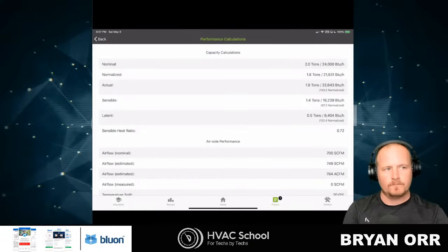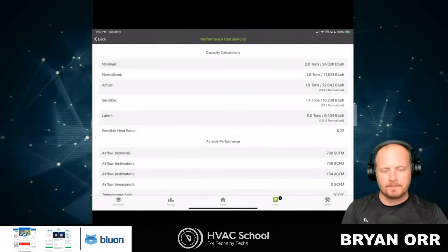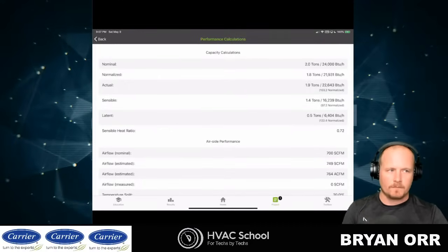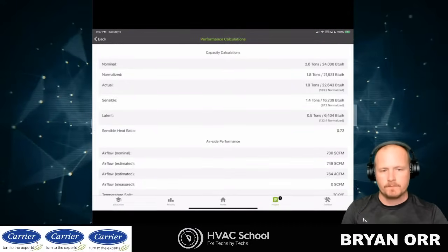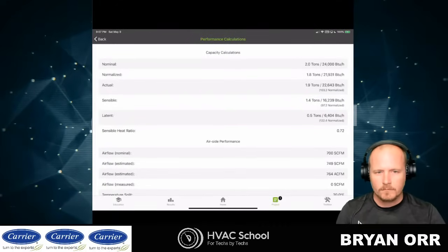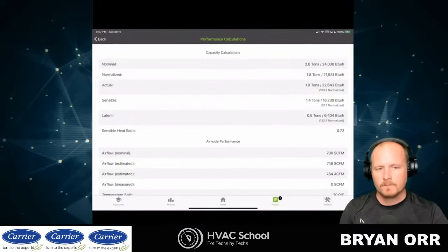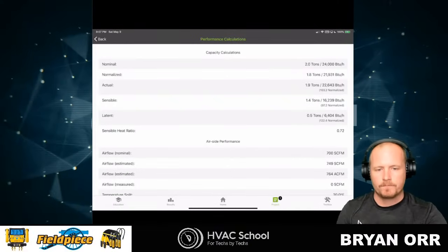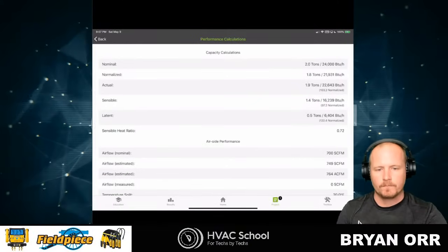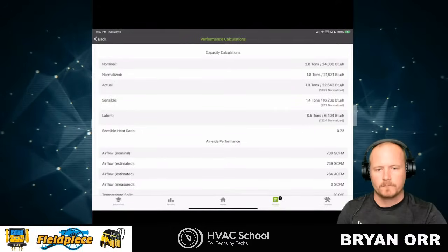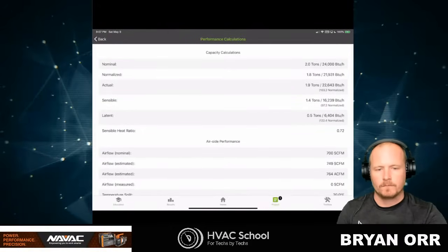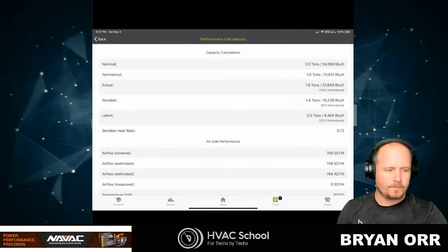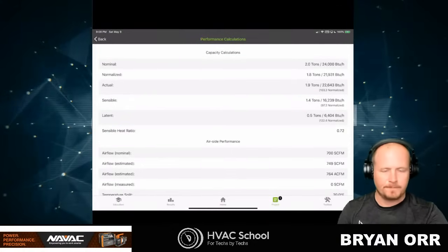So in other words, what do we expect from that 2-ton system? Well, we take into account the return air, wet bulb and dry bulb, the outdoor air temperature, the line set length, the voltage, airflow. All those things contribute to how much cooling we're going to get out of that thing. And so we normalize the capacity. So under the load conditions you're at now, if it was the 24,000 BTU nominal, we expect to see 21,931 BTUs, I guess, is what's on your display there.